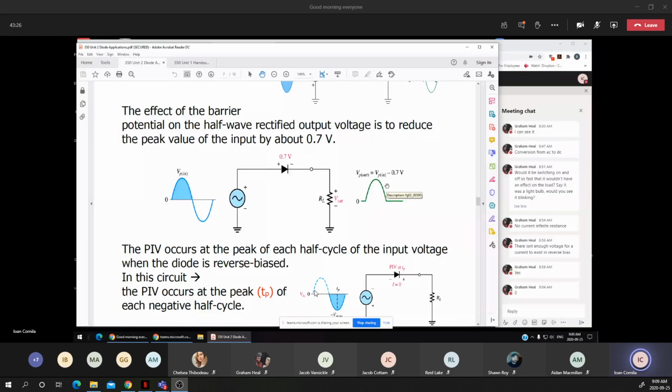If I'm asking for the peak output power, what are we using? The peak output voltage. Knowing the resistance, we can determine the peak output power. In the same way, I may ask for the RMS or the DC output power, which means that I have to use the RMS voltage or the VDC. Using the RMS or using the average gives you the average power. The RMS gives you the RMS power. Using the peak gives you the peak power.